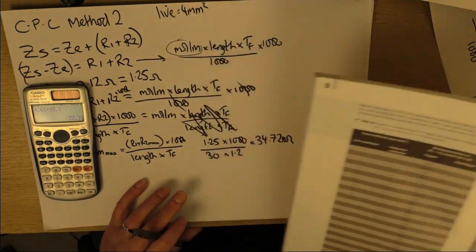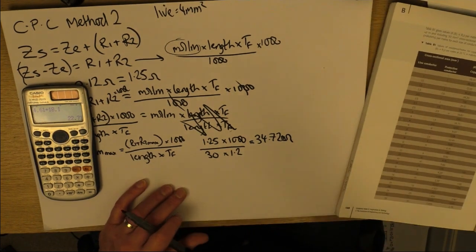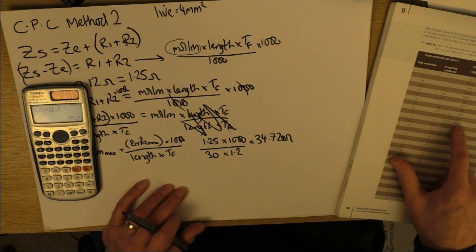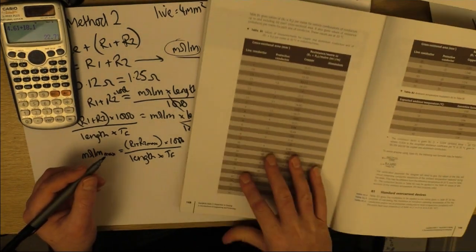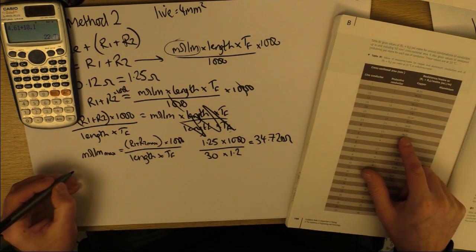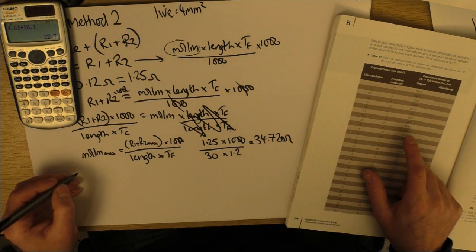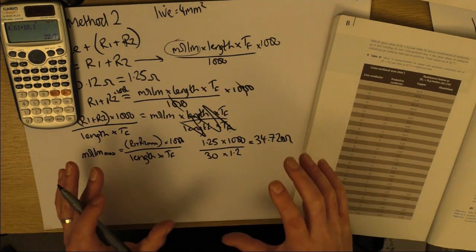I think 1 mil is probably a bit too small mechanically, it might get bashed about a bit, so we could select 1.5. That makes sense. So 16.71, that gives us a value, and we'll need that in a minute because we need to calculate our actual ZS before we use the adiabatic with this method.